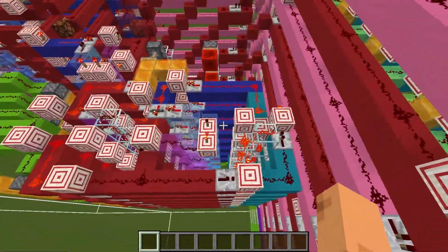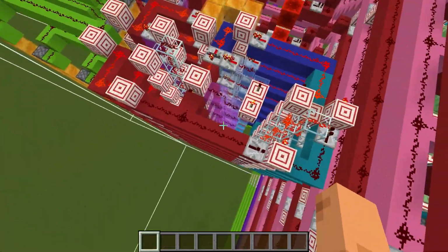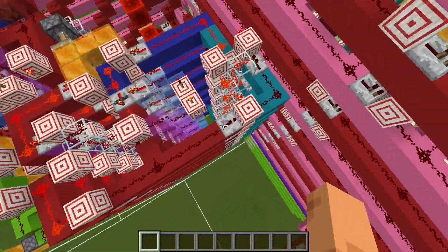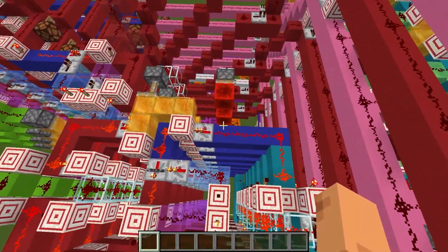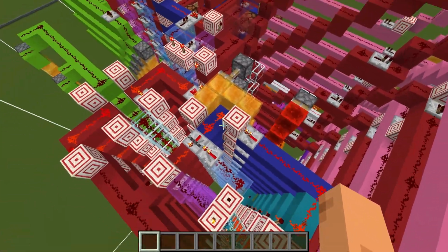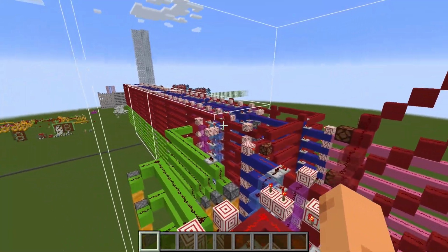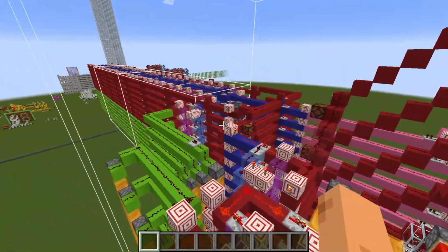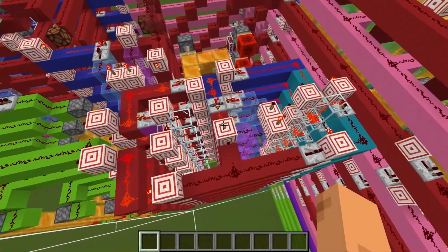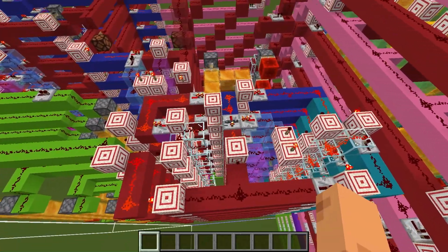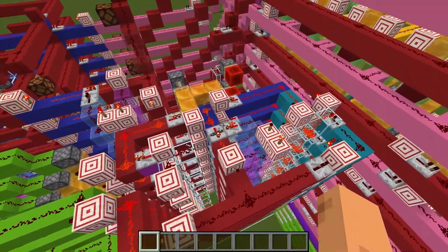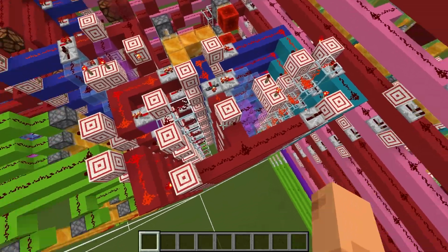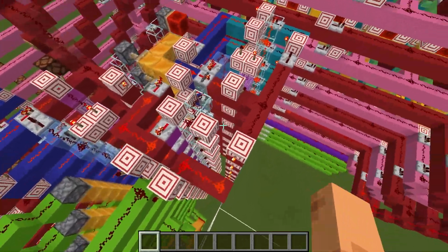And this is what this logic does. It will always increment, but it'll use the incremented program counter or a new address coming in from the previous instruction to figure out where the next instruction will be read from. And that's what this is essentially for.